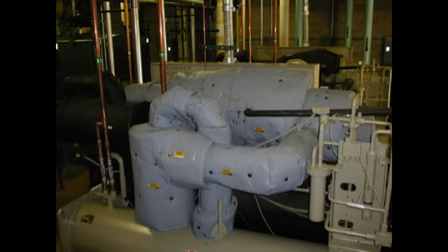And you can often reduce the noise of an item 3 to 5 decibels, or even up to 7 decibels with something like that. With 3 decibels, generally the human ear can tell the difference, but it's not going to make that much difference. You usually want to get up closer, above 5 decibel reduction on something like that, and preferably even up to 10 and above, depending upon how loud it is.